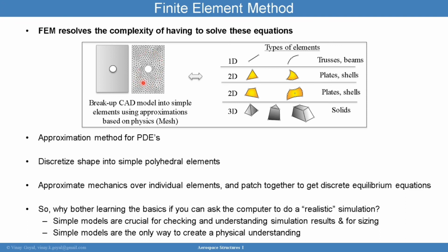So the idea is to solve the PDEs for every element using the one master element, and then connect the elements together via nodes. These triangles meet at vertices, which I'm going to call nodes. And at these nodes is where we're going to be calculating deflections. And the idea then is to approximate the solution of this discretized model.